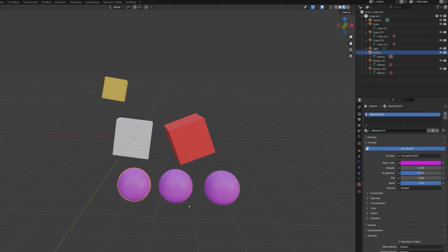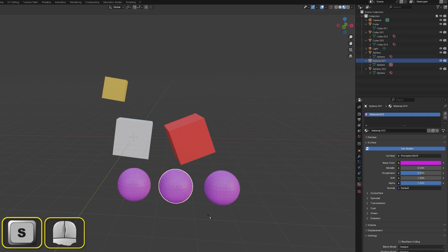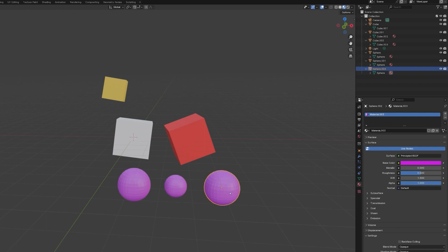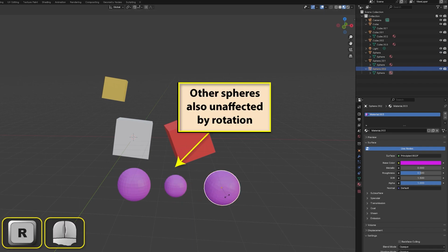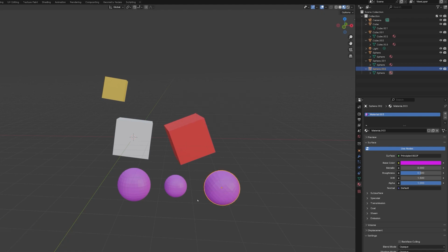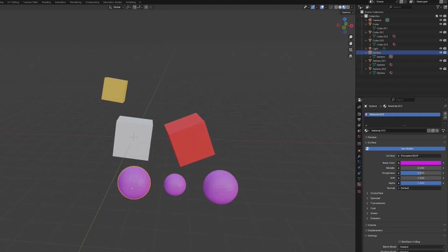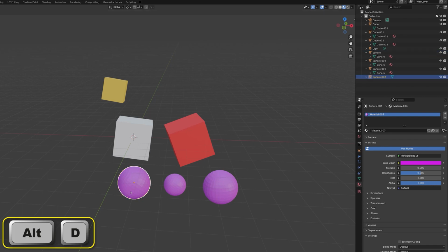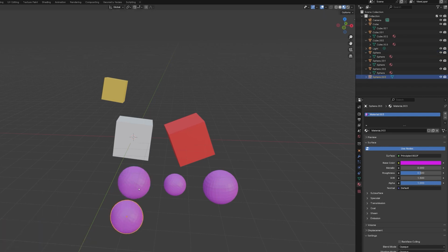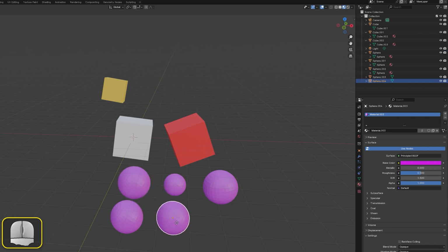And although we can change the size of one without affecting the others, this is only true when working in object mode. If we switch to edit mode, any change of size, shape, orientation, or position of one object also affects the others. When we've created a copy using either Alt-D or Shift-D and completed the automatically initiated move operation, the last op panel will offer us various options.